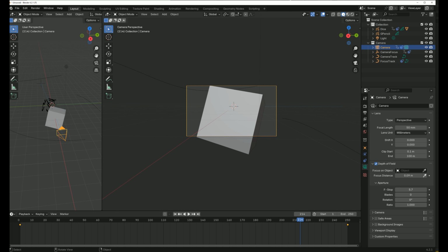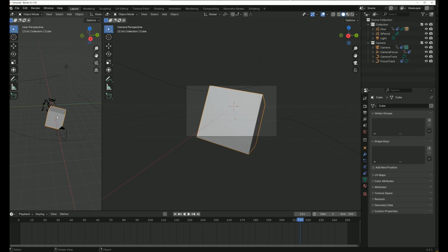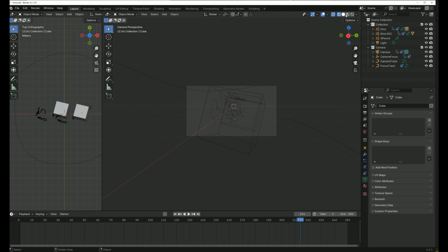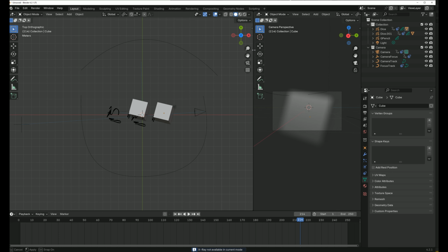And then the last tip and trick here is if you've got a whole bunch of different objects and it's kind of hard to see it. So let's just do top view. Let's do Control C, V, G. Let's just say I have an object behind this object and I want to be able to see it. That's what this little toggle X-ray thing is for. Now I can see what's behind it, and also wireframe mode as well. So those are just different view modes. I'm typically on my camera side, I'm on rendered, and I don't have my X-ray mode on. And then on this side, I'm typically just on your solids view. So those are the two things.